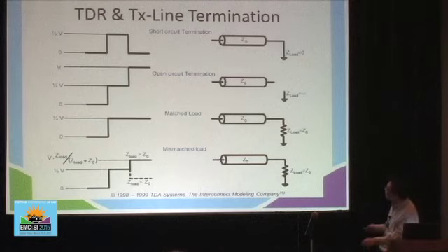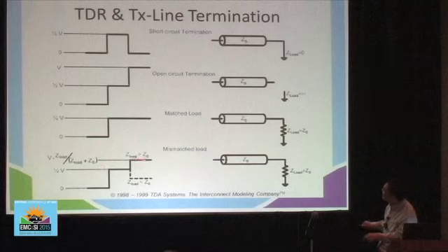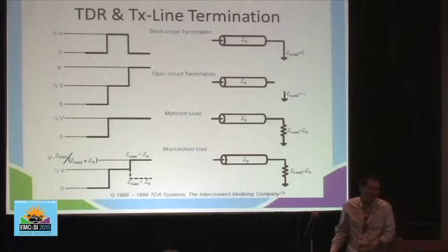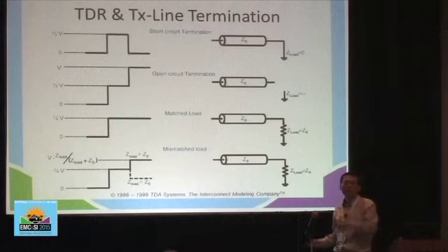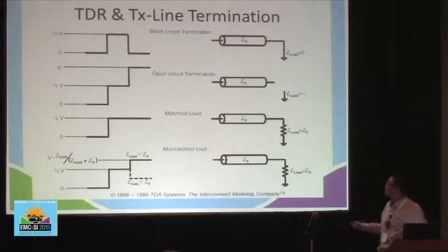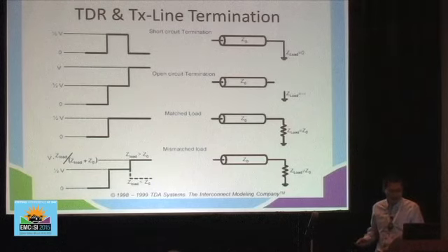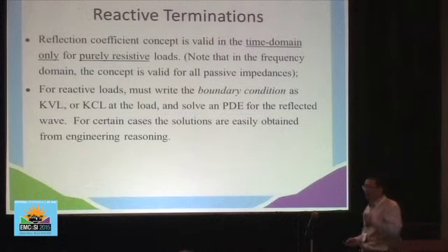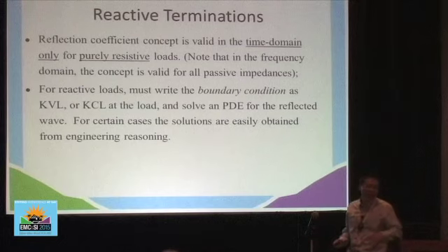And in general, if you have some resistive load greater than 50 ohm, then at this location you would see a voltage greater than the initial voltage. If the voltage here is smaller than the initial voltage, this load must be smaller than the characteristic impedance. So from the TDR measurement, if you know the topology of your device, you can easily come up with this understanding.